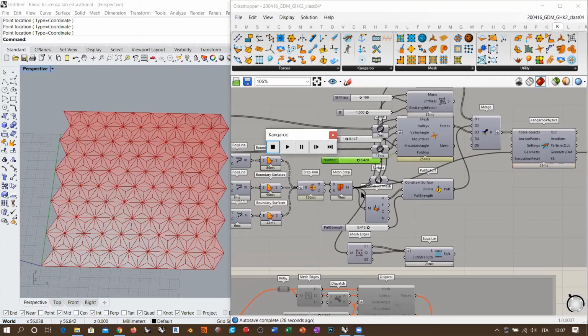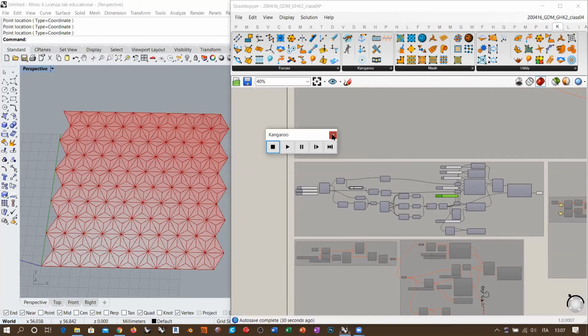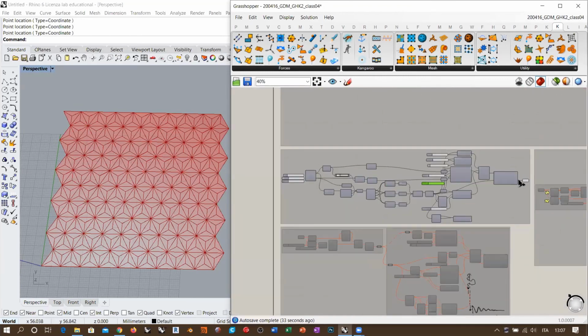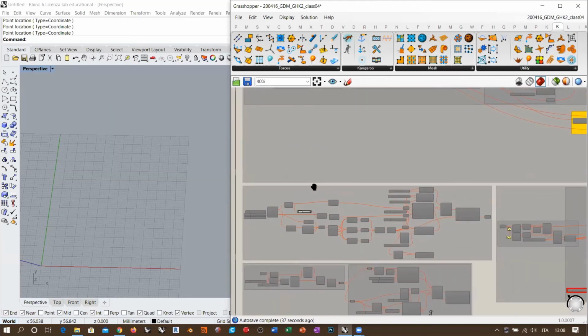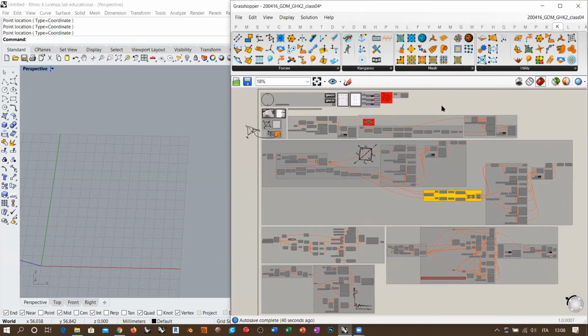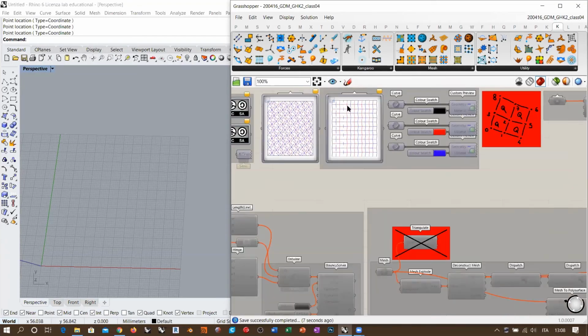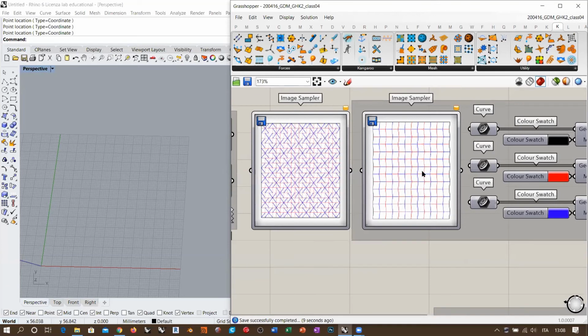Okay, so that's it basically for the origami simulation. Remember just the basic concepts. If you want to work with some complex geometry, I do recommend that you take into account the possibility of using Kangaroo 099, because it makes it possible to work not with a simple hinge, like along the diagonal of a quad face, but also using directly valleys and creases, or valleys and mountains, which is the proper way of creating complex origami.